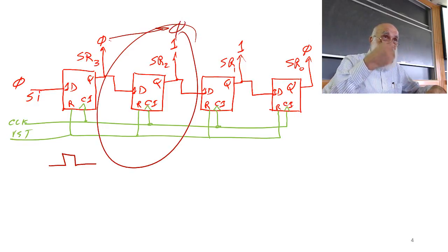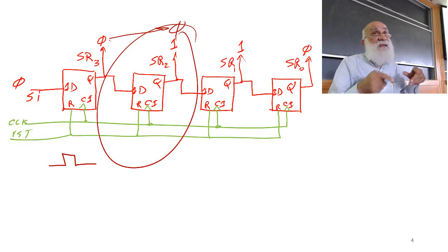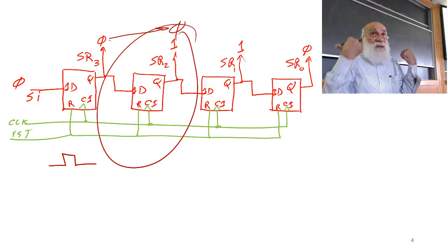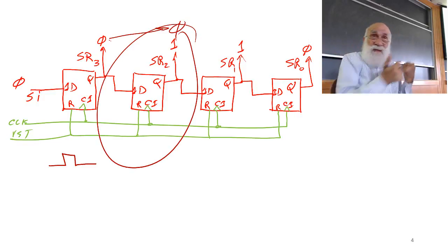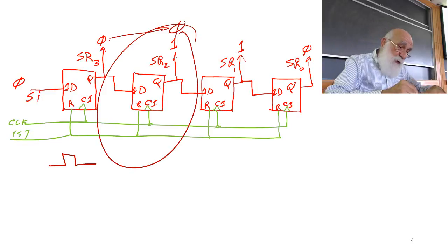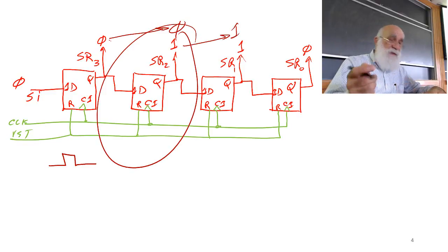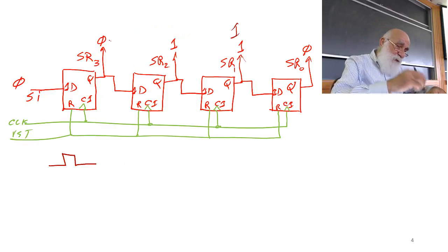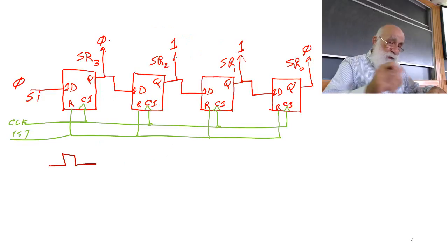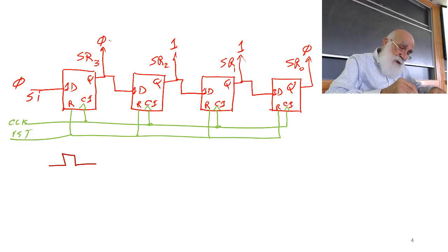Okay. But this is not the 0 that will go into the output of SR1. Actually, SR1, since it is taking the input simultaneous with SR2 taking the input, the 1 is the one that goes into the output of that. Okay? So that you don't get confused when you are doing this, usually best is to start from the right-hand side. Okay? Start from the right hand side.